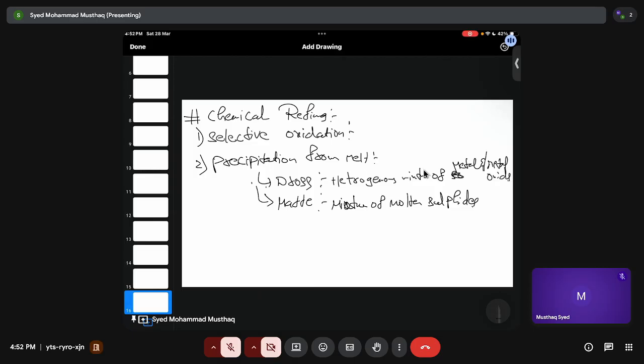Okay, and how does it happen? For example, mostly the dross we talk about comes from aluminum, the alumina dross. So in alumina dross you have alumina and some amount of pure aluminum trapped in that alumina. Some of the aluminum will be trapped as a liquid on the alumina solid particles.